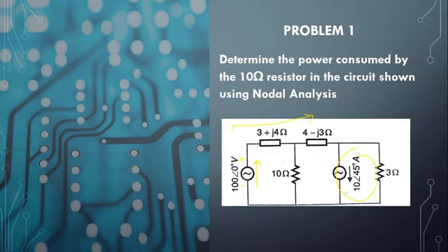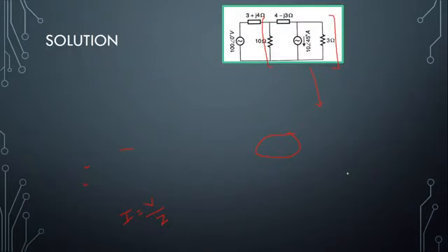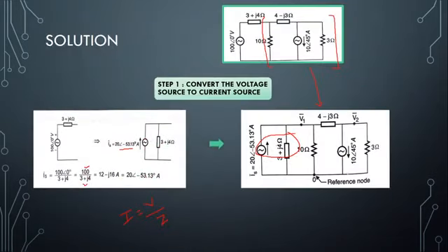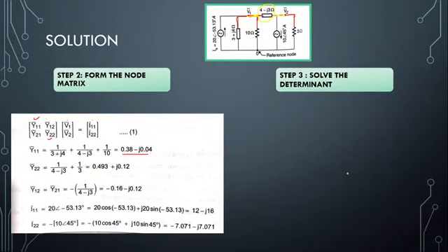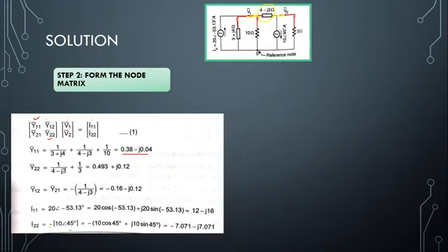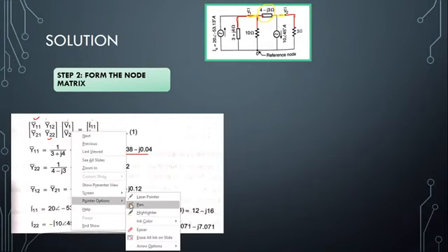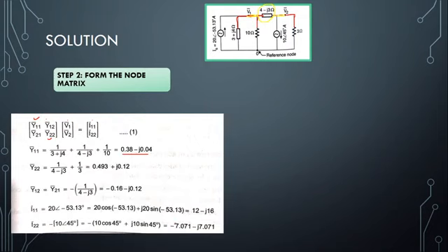But this is in the opposite direction of that, so we will assume this current to be of a negative magnitude. That is why we have minus 10 angle 45, which is minus 10 cos 45 plus J sine 45. Fine. That is how we have got this.